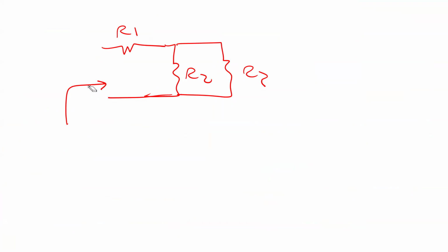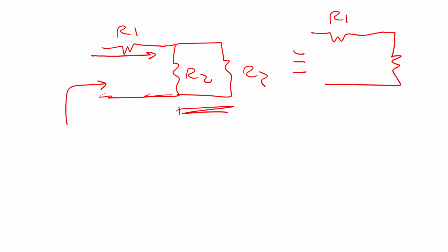Okay, look here. What happens is that the current is going to come here, and then it's going to split between these two. It's very obvious that these two resistances are parallel. So I can say this is equal to R1, and then another resistance equivalent to these two resistors, because these two are in parallel, which is R2 times R3 divided by R2 plus R3. I'm not going to do it in one step. I am going to do it in several steps.